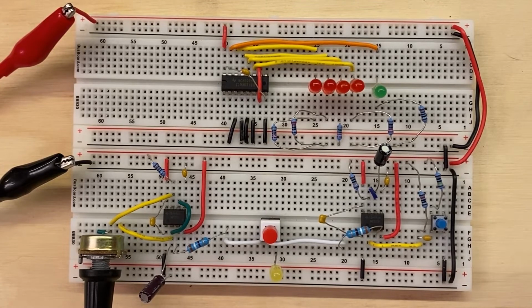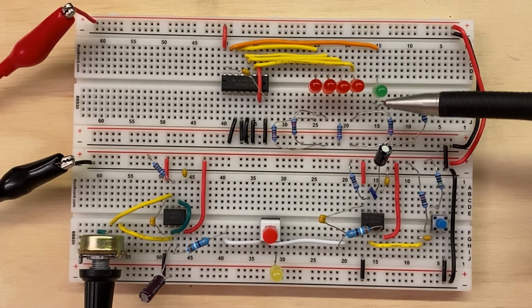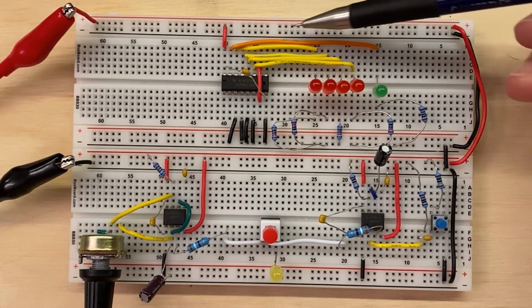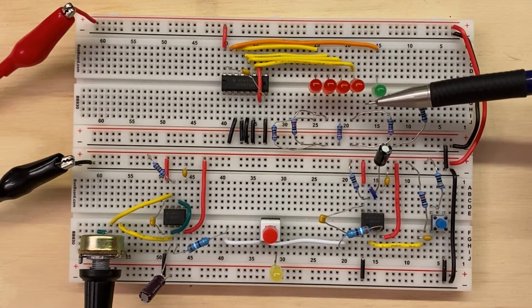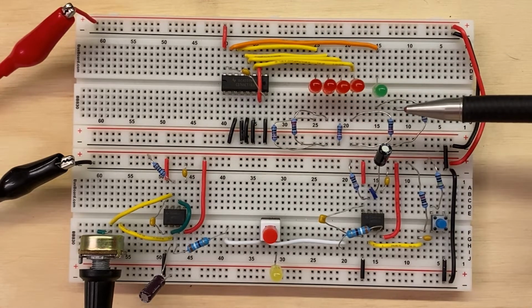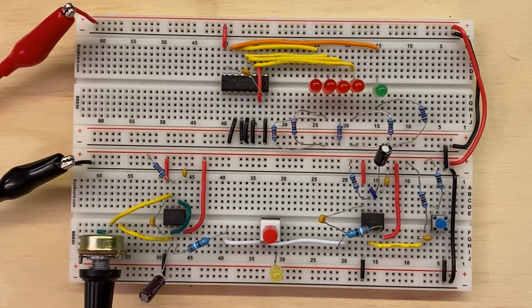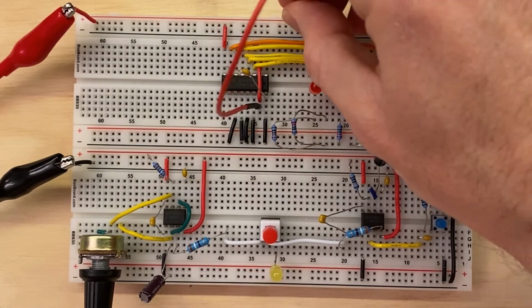That's not good. And our clock pin is here, and the master reset pin is here. And this little green LED, if you follow this orange wire, that's the TC pin. So this will light up to say that the count is full. So basically, when all these reds are lit up, this will light up too. Okay, so let's set up our control pins. So first, we have the enable, and we've got to put that to high.